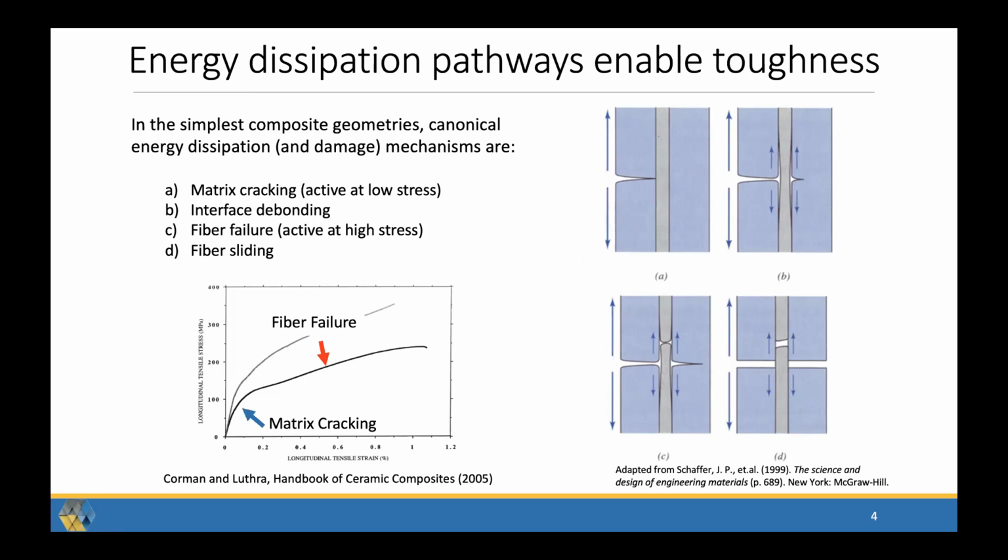And so you start to hear when you put these acoustic emission sensors on, which is just listening, right? So acoustic emission, anything, when it breaks, it makes a noise. You break a piece of clay, you'll hear the noise. This is the same idea, except it's at a much, much higher frequency. So we put these sensors on and we can hear the sounds that these damage mechanisms are making.